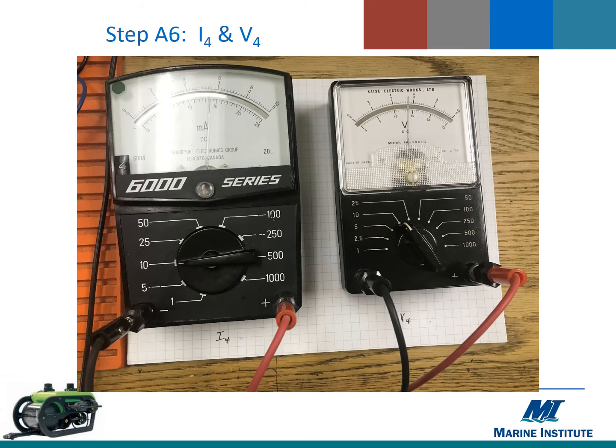And so we look at our close-up now of the meters for resistor 4. Hopefully we won't find a mistake in them this time. We start with the voltage meter now, and you'll notice we've moved the voltmeter selector switch to the 10 volt scale. It tells us that now 10 volts is the maximum measurement or full scale deflection. So we should use the very top set of numbers here to make our measurement. You'll notice 4 halfway, then here's 5, 6, and that meter needle there is almost exactly halfway between 5 and 6, so we measured that as 5.5 volts.